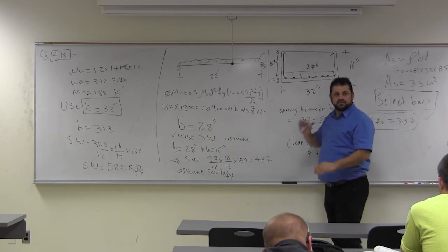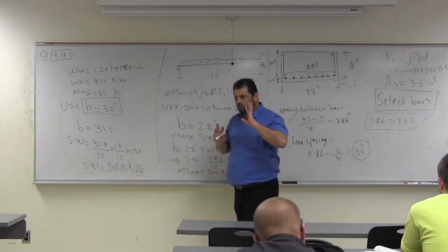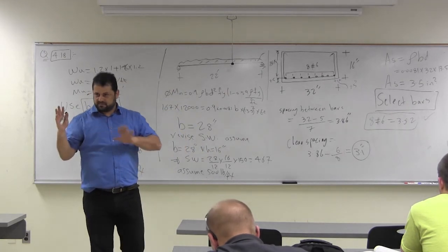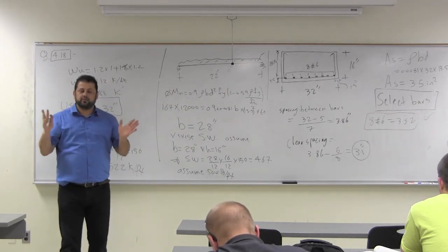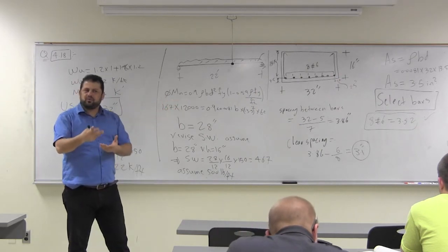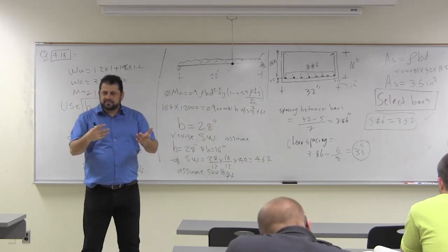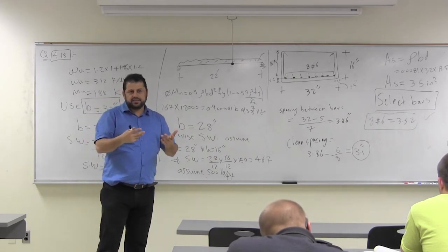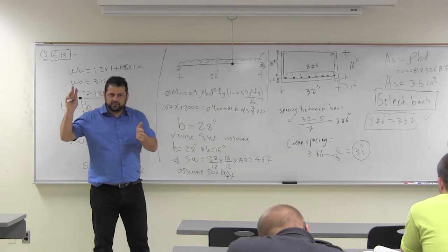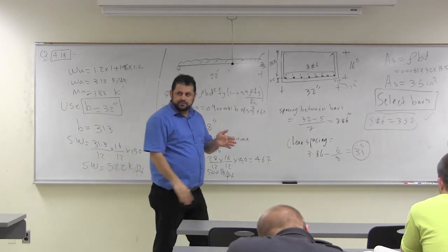That's over the stirrups. If I tell you in the question the cover over the stirrups is that much, it's different than when I tell you the cover over the bars is that much. Or if I tell you the word cover, we assume to the center of the bar. So usually the spacing is 1.5 inch, something like that. 1.5 inch, 1 inch, that's the closest you can get. Sometimes you can go to 1, if you know that your aggregate is less than 1 inch.